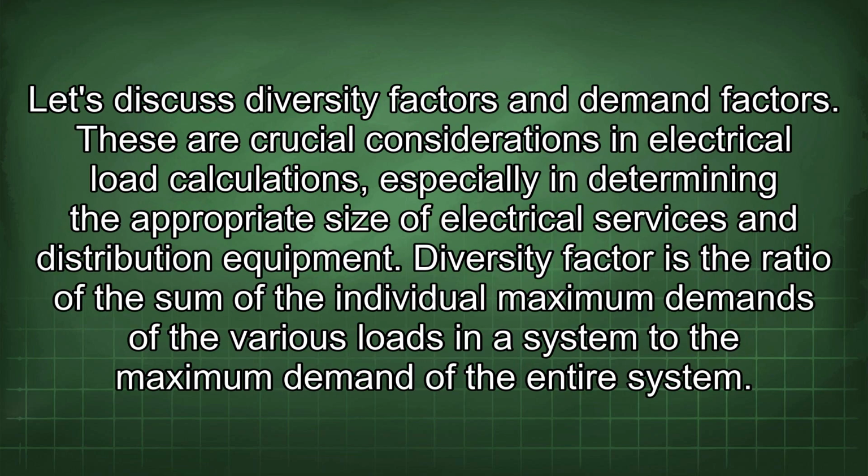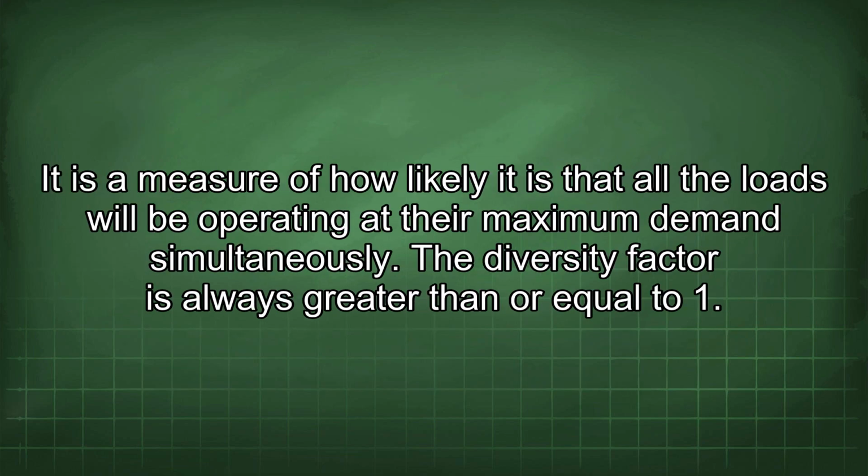Let's discuss diversity factors and demand factors. These are crucial considerations in electrical load calculations, especially in determining the appropriate size of electrical services and distribution equipment. Diversity factor is the ratio of the sum of the individual maximum demands of the various loads in a system to the maximum demand of the entire system. It is a measure of how likely it is that all the loads will be operating at their maximum demand simultaneously. The diversity factor is always greater than or equal to 1.